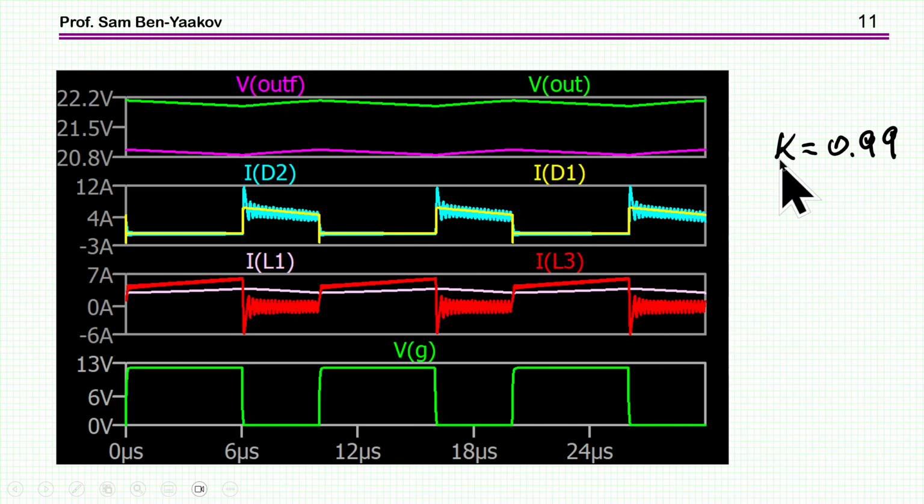Now, once I reduce the coupling coefficient, then in Flyback, obviously, I'm starting to get some oscillation and spikes and overshoots, etc. We don't see it in the Sepic. Everything is smooth and nice. You see the current of the output diode, very smooth. We see also the primary inductor current, very smooth, no oscillation, nothing. So you see that there is a big benefit in this Sepic in that it is not switching the leakage on and off with the open circuit, but rather it's locked within the loop.